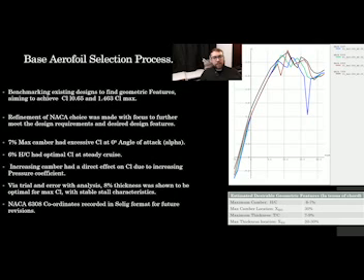A range of NACAs was simulated to ensure the NACA chosen was closest to optimum. 7% max camber was excessive in terms of CL at 0 degree alpha and would abruptly stall at 10 degrees, whereas 6% produced optimal CL for steady cruise. Increasing camber can have a direct effect on CL due to increasing pressure coefficients on the airfoil.